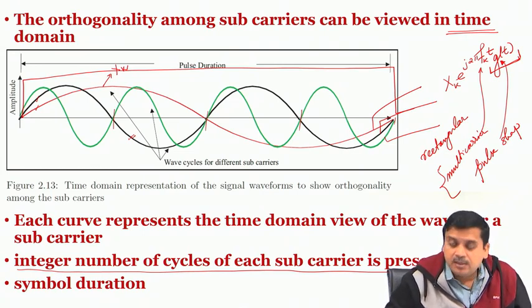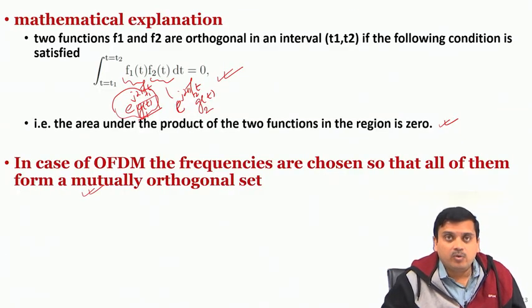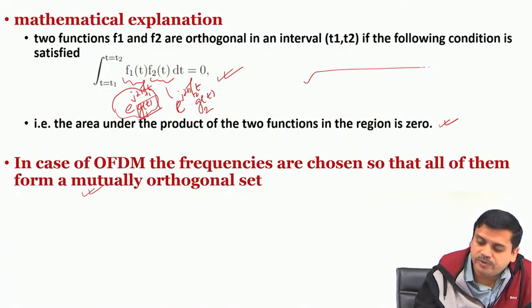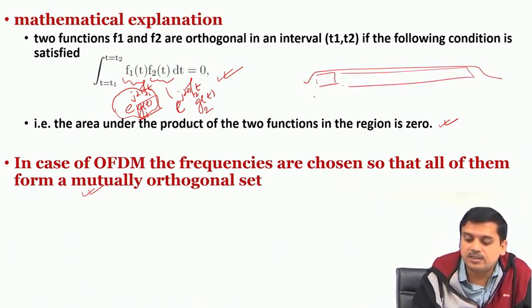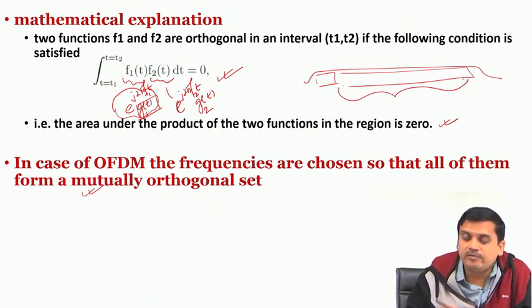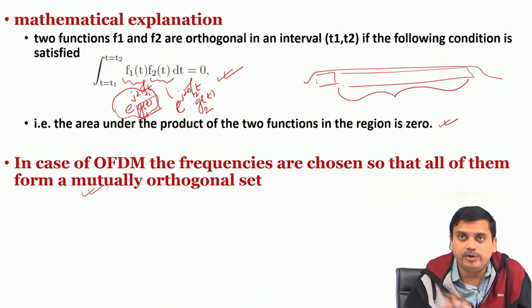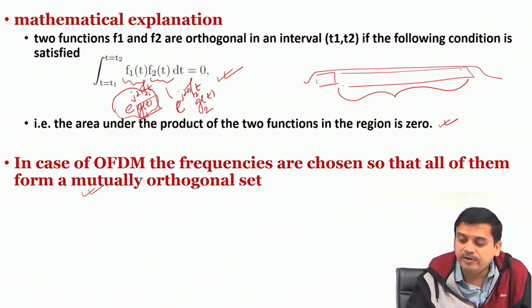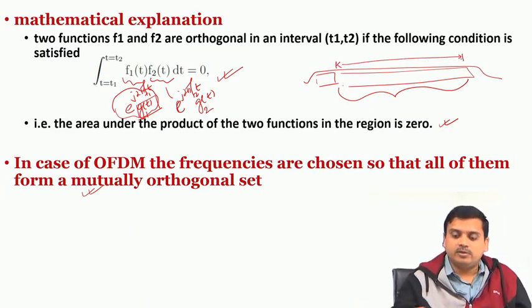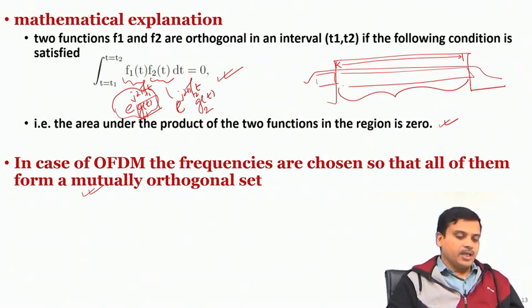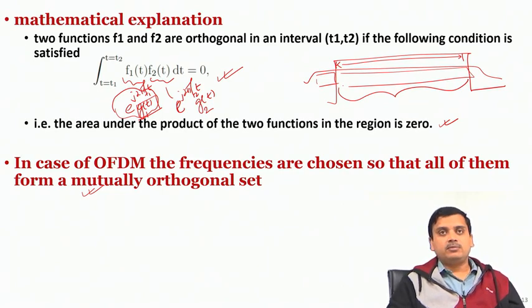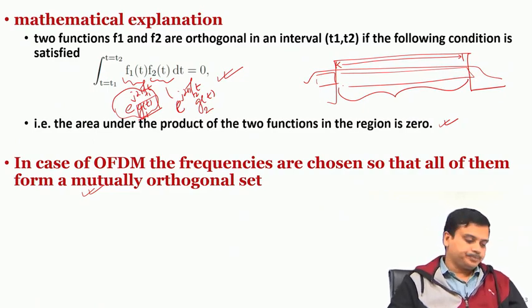Now, one may think of a question about how one would think of windowing. We will discuss windowing. Some people already know about windowing at this stage. There is also a cyclic prefix which we will discuss. In the period of interest, where we are actually doing the processing, you will find that the pulse amplitude remains constant. So, if we are interested in this particular section, over that period we can assume a rectangular shape, and the spectrum that we have considered to be sinc in all the discussions we have had is primarily because of having considered a rectangular pulse shape.